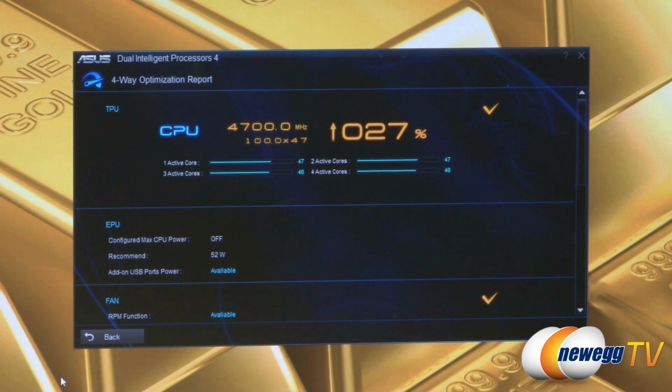We can see right here, it's completed our overclock. We have 4.7 gigahertz on 2 cores, and then 4.6 gigahertz on 4 cores. Keep in mind that the frequency could go even higher than this if we increased our fixed voltage level. But we've been very cautious that we don't want an overzealous level of voltage being applied, even if that could give us more frequency. At the end of the day, it's very important to us that we give you safety, but high performance at the same time. So our fixed maximum voltage level is going to be 1.275 volts. Okay. We won't exceed that marker.